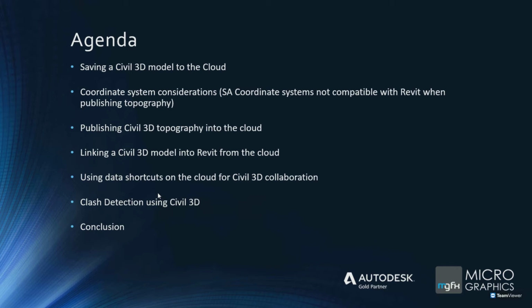Some of our clients have worked there, in Vietnam and in Mauritius. Yemen and Vietnam, because they also swap the X and the Y coordinate systems, just like we do in South Africa. And then Mauritius, because they often use a very specific coordinate system, which can be problematic if you want to work between different software. So it might be advantageous to choose a different coordinate system there.